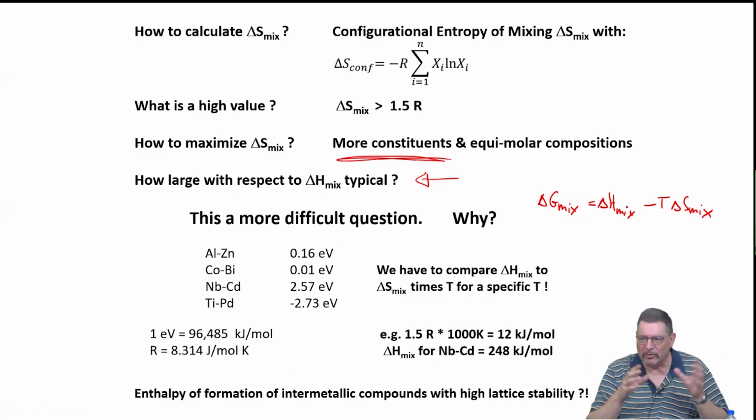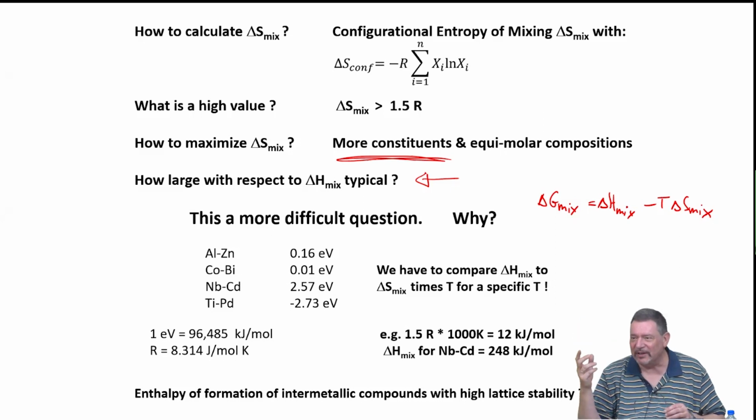If you are now to select a new high entropy system, what does this tell you in terms of how you select the atoms you want to mix in order to get a stable solid solution phase, a high entropy alloy? Just from looking at the periodic table, not looking into CALPHAD and everything, just a quick glance, like you have an idea or you want to create an idea.